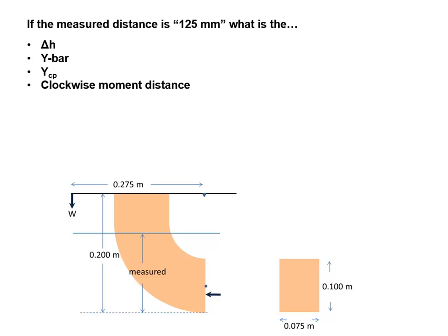The other issue is, remember in chemistry when you're doing experiments, the meniscus, where the water level rises up on the edge. If someone used the top face of the water meniscus instead of the bottom, that's another source of error. The other thing is if it wasn't in equilibrium, if it wasn't actually level, so maybe you put in too much water or not enough water, and it wasn't in the genuine equilibrium condition that you thought it was. Those are, I think, probably the main sources of error.